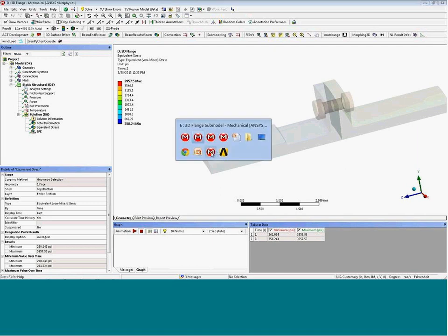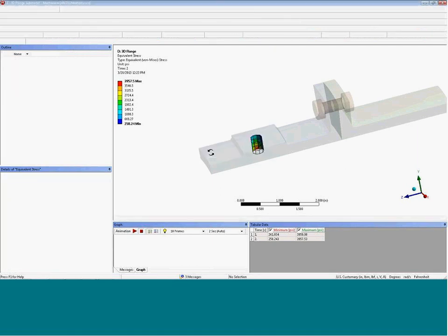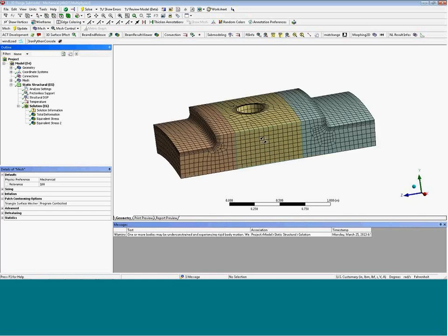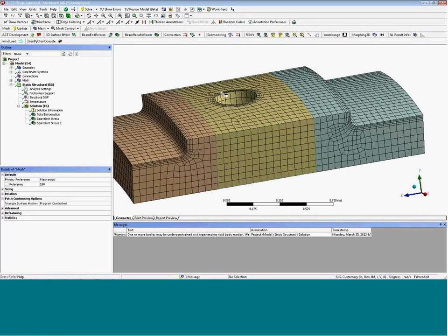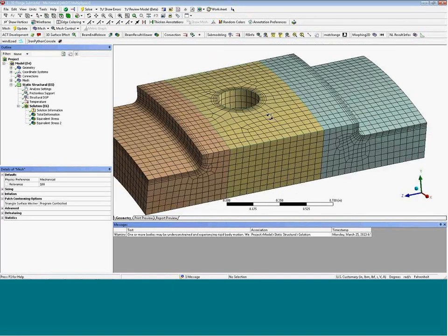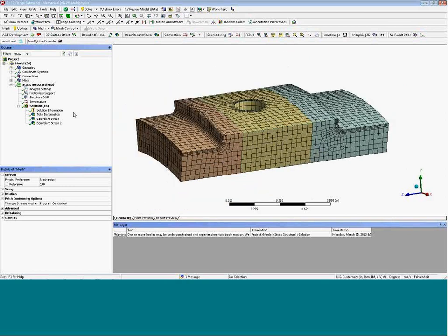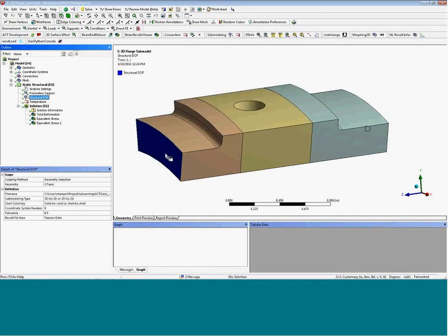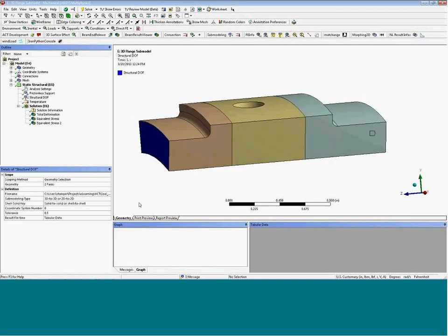So then we can add and use the submodeling extension for displacement. So we build a model of just this localized region. We have a much finer mesh on here, with some elements near the surface. And we apply this submodeling for displacement to map it. And click the 2 faces here. That's going to get that mapping 3D to 3D. It could also be 2D to 3D, 3D to 3D, shell to solid.